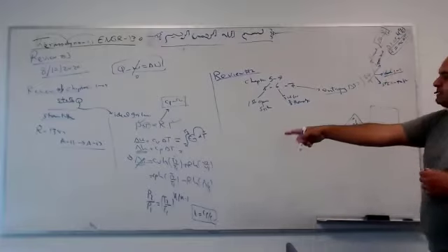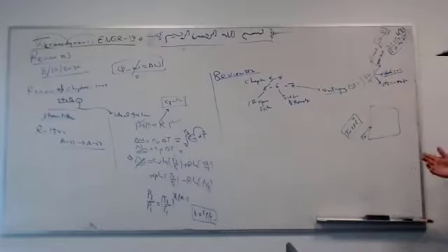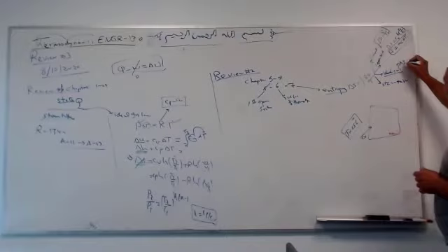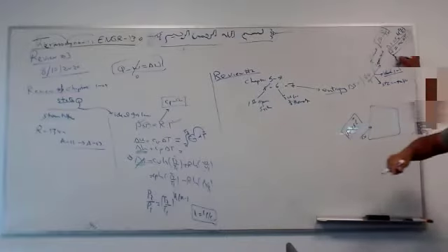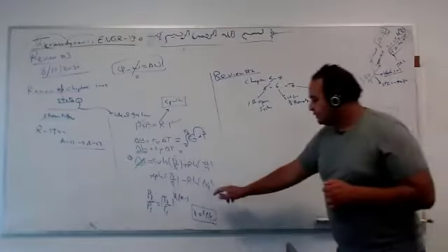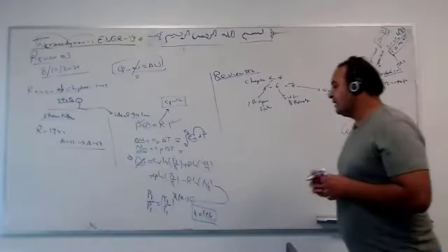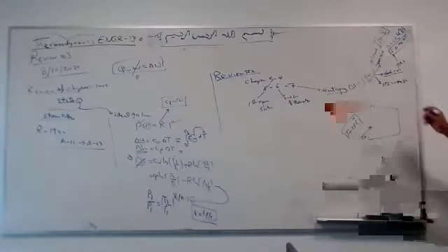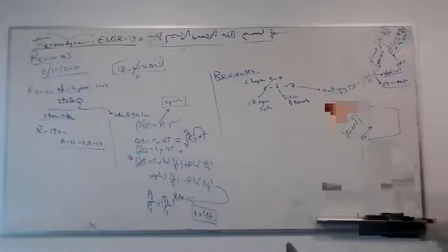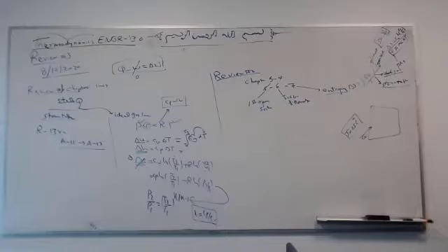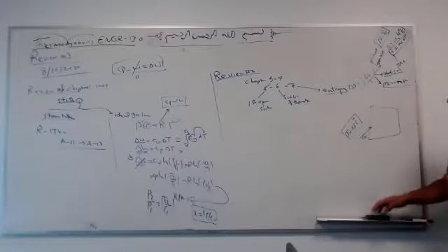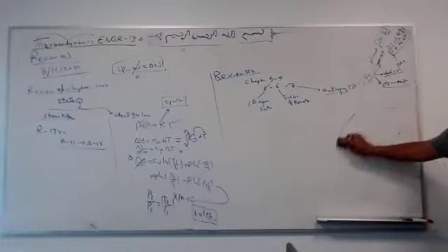For ideal gas, these are the two equations. I need you to know where we derive them from, the T delta S, and how to change from them to isentropic. We started from T delta S. Actually, we proved this, and we proved those, and we also proved this. So this one will be given, like in the exam. For steam tables, we have an additional column added to our system, which is the entropy column, joule per kilogram Kelvin. It's per unit Kelvin. It represents how much mess you have.